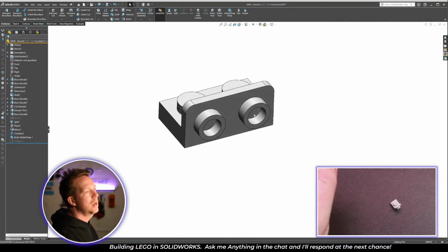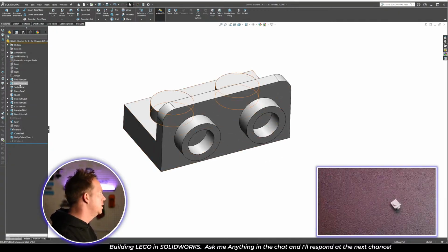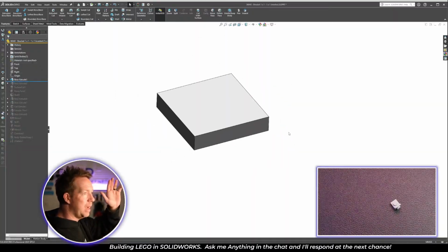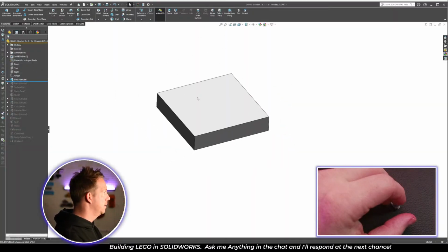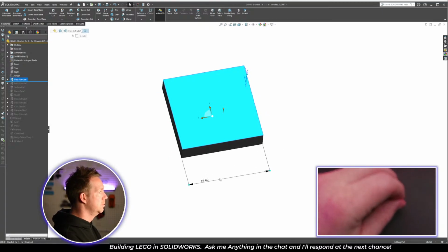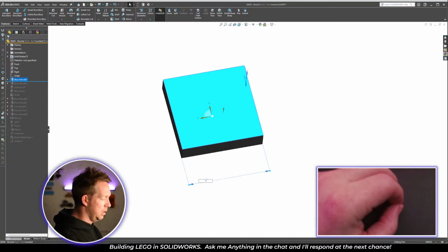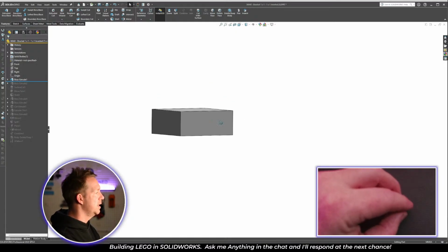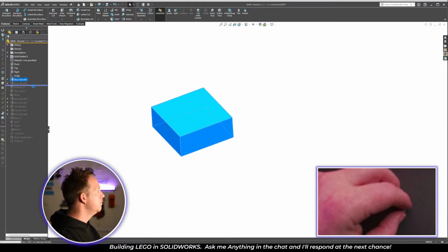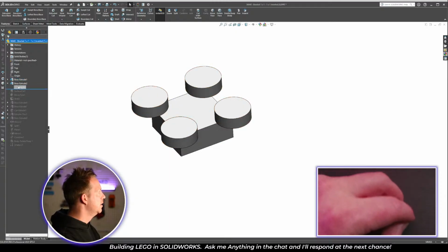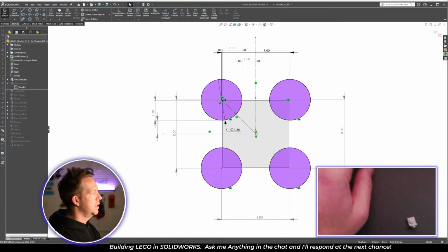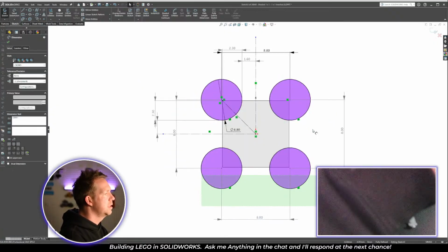And when I'm doing this kind of work, what I like to do is minimize the errors that I see. So I might roll all the way back and start with something simple. I'm going to start here and just change this to the square that it needs to be, 7.8 by 7.8. I know that that's going to cause an issue here, but that's fine. I'm going to delete all those that I don't need and just keep the original.